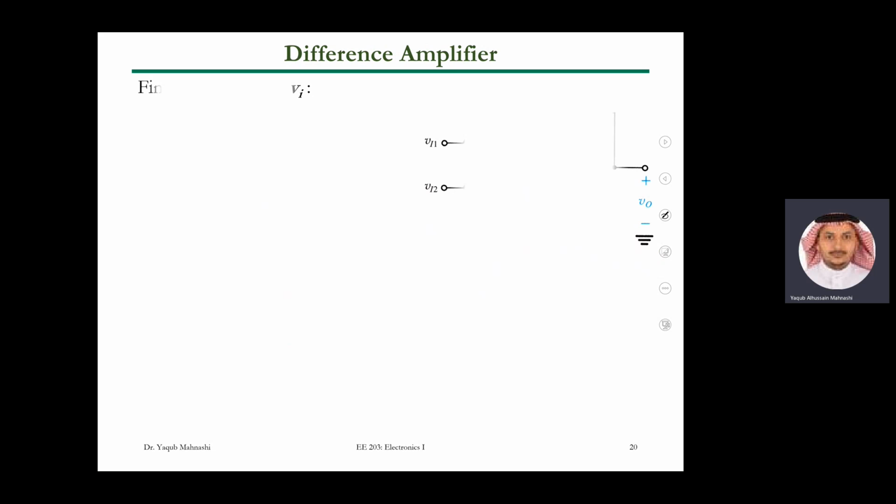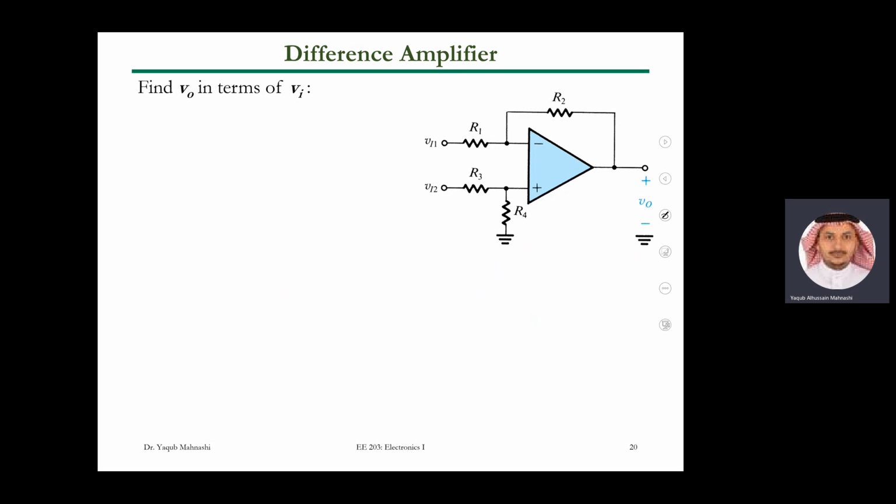Okay, small one. So let's now switch gears to another interesting application of the OPAMP. Let's find the expression for the output over the input, the transfer function here, first without assumption. So we have 4 different resistors, but then at the end of the day, you will make R4 equal R2, R3 equal R1, because this is a difference amplifier. So in a difference amplifier, R1 equals R3, and R2 equals R4. We usually design the difference amplifier to be like that. But let's first have it as is.